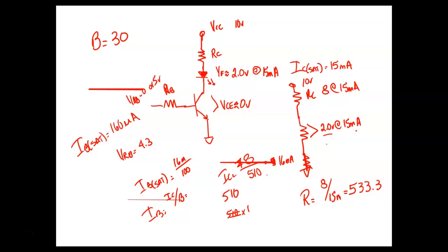All we're trying to do is guarantee that it's going to saturate no matter what we do, as long as I put about 5 volts on the input. Even the 5 volts is not guaranteed to be perfect. So if I design it around exactly 5 volts and exactly this and exactly that, then it may or may not saturate. What we're trying to do is design it so it always saturates. I could use a beta of 40, but that means sometimes it would saturate, sometimes it wouldn't. It might saturate in the summer, but not in the winter.